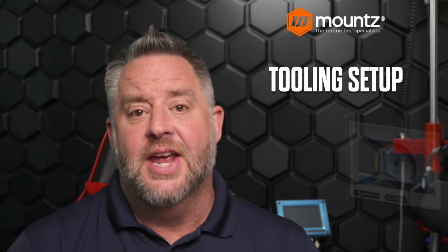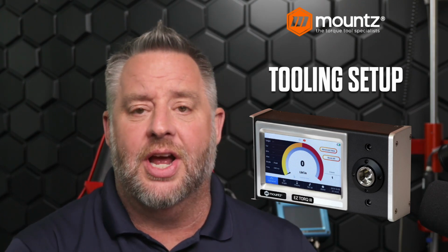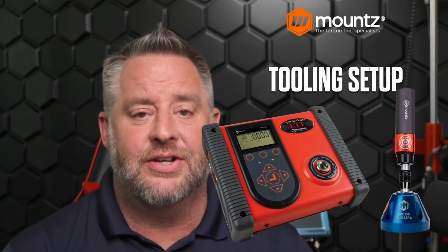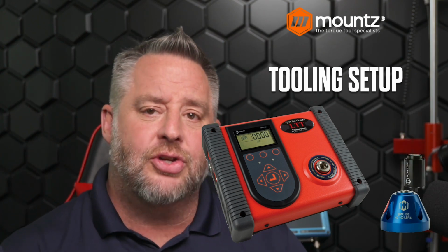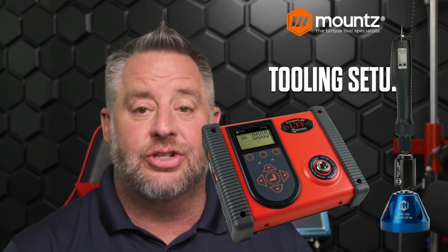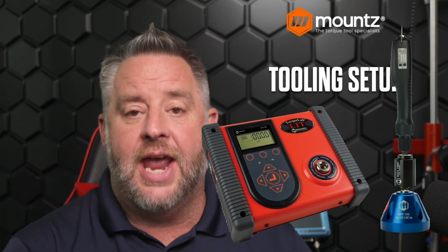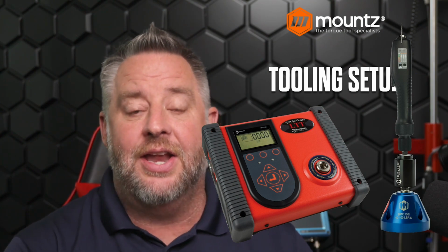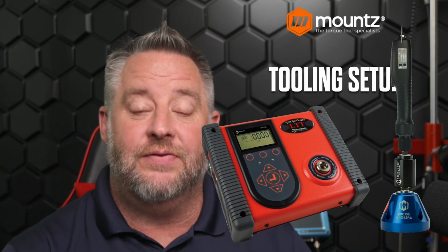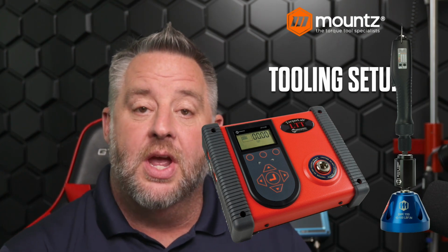And then that is typically done with an analyzer like this, where you have an internal sensor that you can use, or you could even use an analyzer like this that also has a torque sensor built into it, but it also has the ability to expand the range of the analyzer by adding additional sensors to it. So for example, if the internal range of the analyzer went from 5 to 50 inch-pounds, but we also then needed to get up to 250 inch-pounds, we could then add another sensor that would have a range of 25 to 250 inch-pounds, giving us the ability to test outside of the range of the internal, but we're still utilizing that analyzer for that ability.